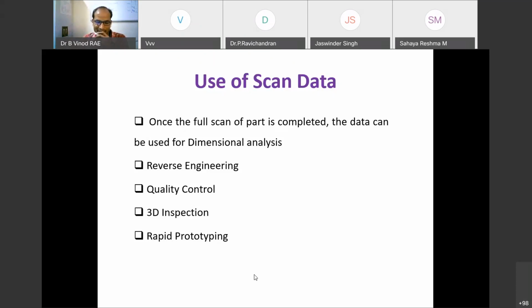This watertight STL point cloud data is taken to the 3D printing machine. The 3D printing machine needs an input file in .stl format, so we can input it into the machine. Next, the 3D printing machine slices the CAD STL file layer by layer. Then we start printing from the bottom layer to the top layer. Finally, we get the whole part.